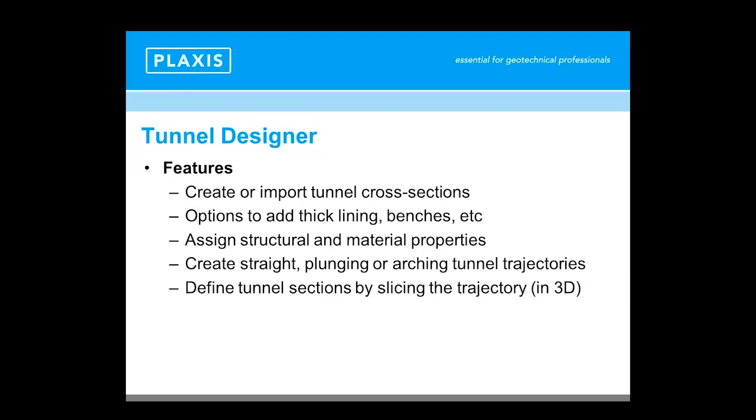So the most relevant features of the tunnel designer are the following. The possibility, of course, to create tunnel cross-sections, but also to import them. We have options to add thick lining, benches, and so on. And also the possibility to assign all relevant structural and material properties that belong to the tunnel.